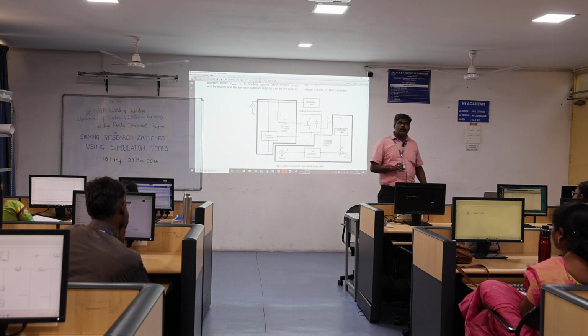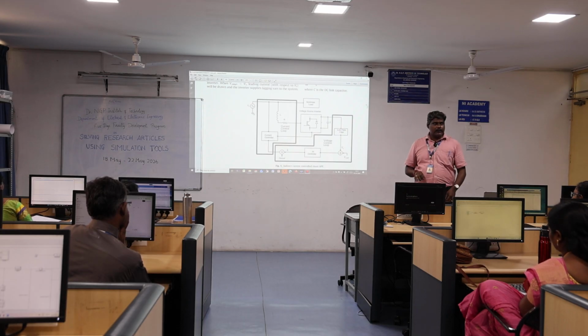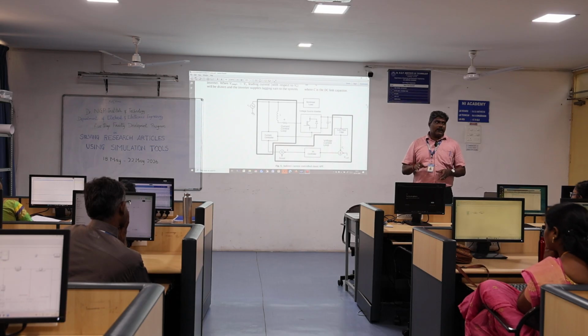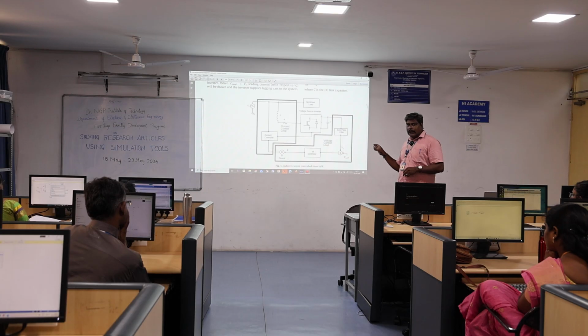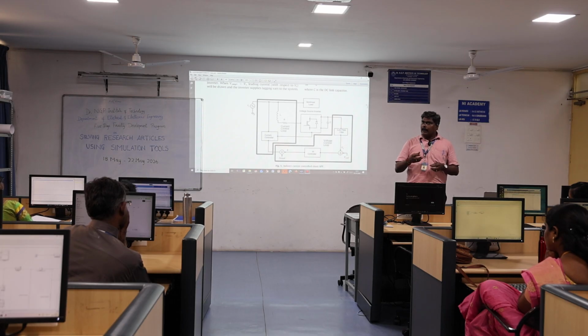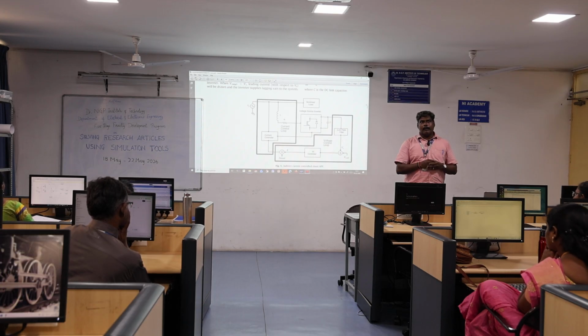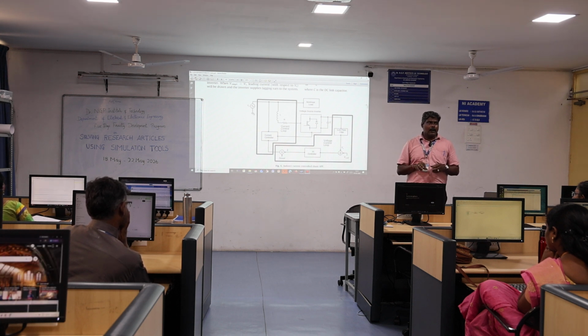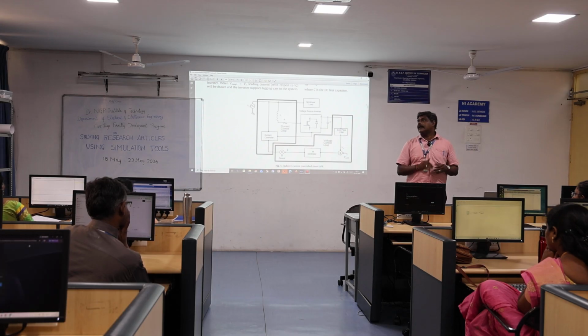Normally, why we go for the proportional integral controller means the first point is to reduce the steady state error. Next, to improve the transient response. So this is the main reason we go for the proportional integral controller. For example, when you apply the P controller alone for any system, it is a proportional gain value. When you have more gain, what will happen? You have more steady state error. But at the same time, you have a good transient response, like a startup transient response.